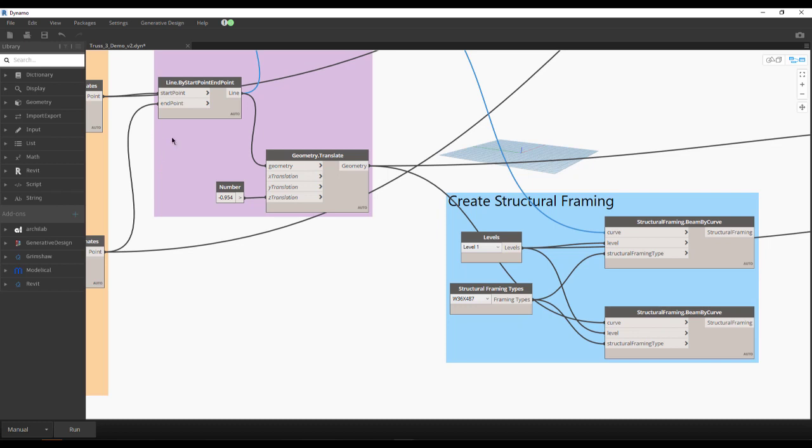Just like we talked about in our PowerPoint, we have inputs coming in, functions happening within these nodes, and then output coming out. What's unique is that we have many different functions, with the output of one becoming the input into another. You can see here, for our framing elements, we create those and use the output from that specific node as the input into this one.